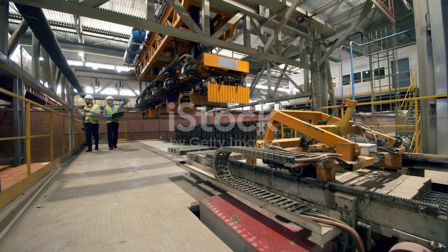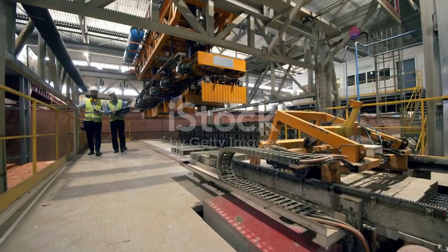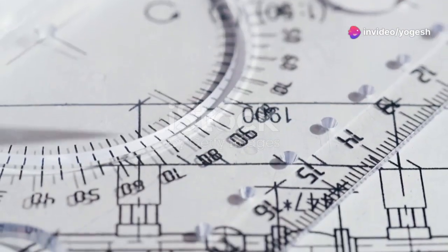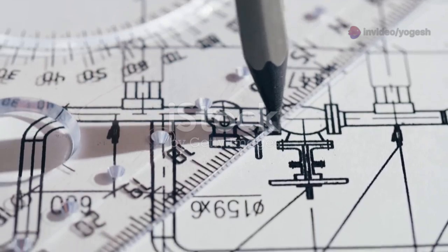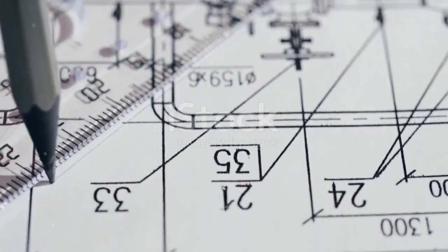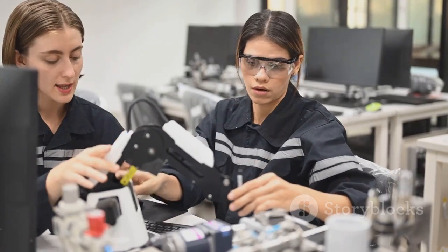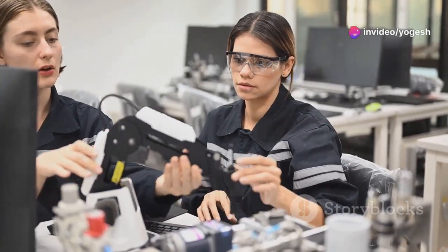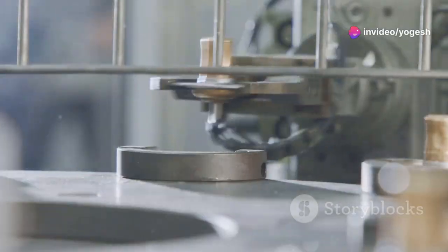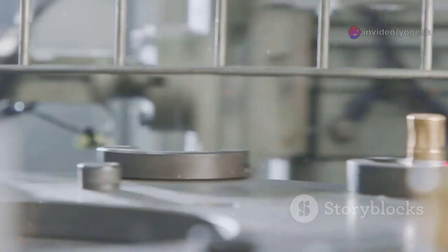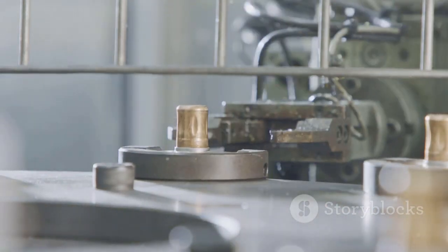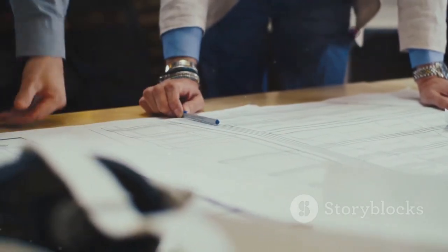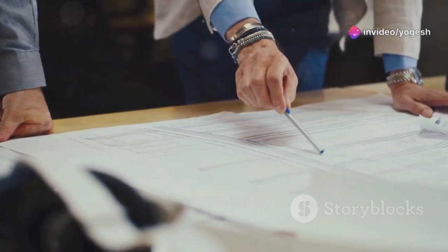A well-defined assembly sequence is the backbone of manufacturing. It translates design into reality, using balloon numbering, stage tables, and sectional views as a universal language. This clarity eliminates ambiguity, reduces errors, and ensures every product is built to the highest standard. The benefits: faster assembly, lower costs, better quality, and improved safety. It also serves as permanent documentation for training and troubleshooting.